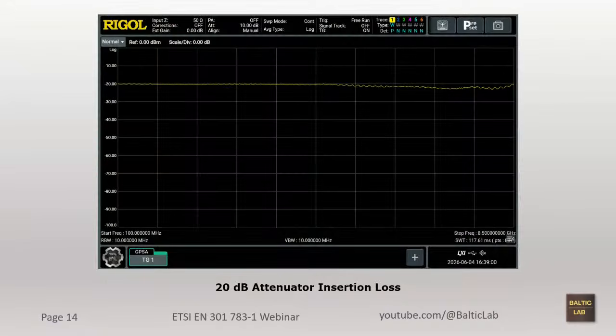And this is also an excellent attenuator, which you should always verify. You see it's really flat. Wait, where's my mouse arrow there? This is up to 8.5 gigahertz up here. And I'm going to say 4.5, 5 gigahertz. It's very good. I mean, there's some ripple starting to appear, but you can correct that easily, which we will also get to a little later.